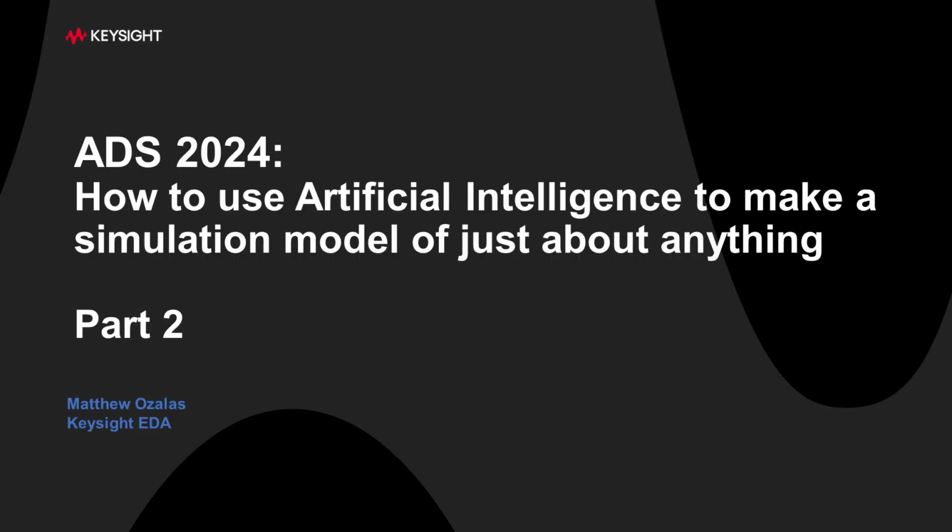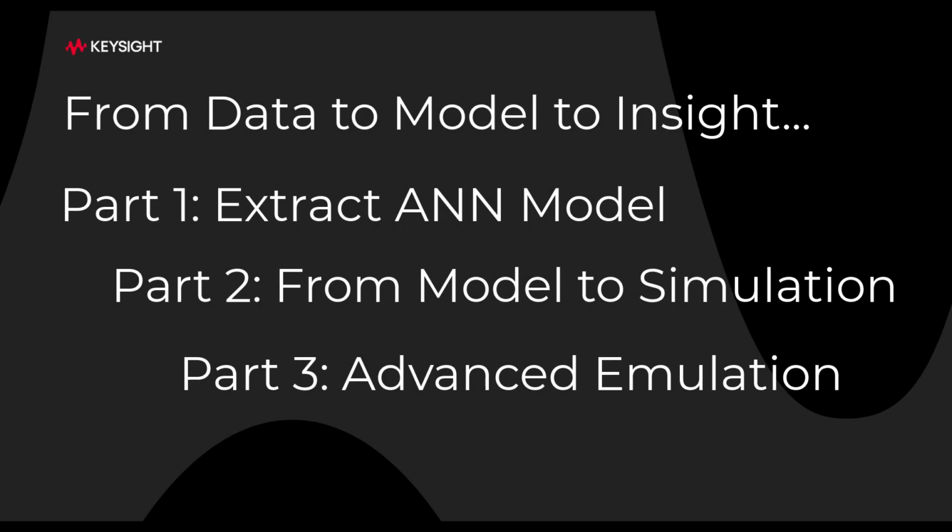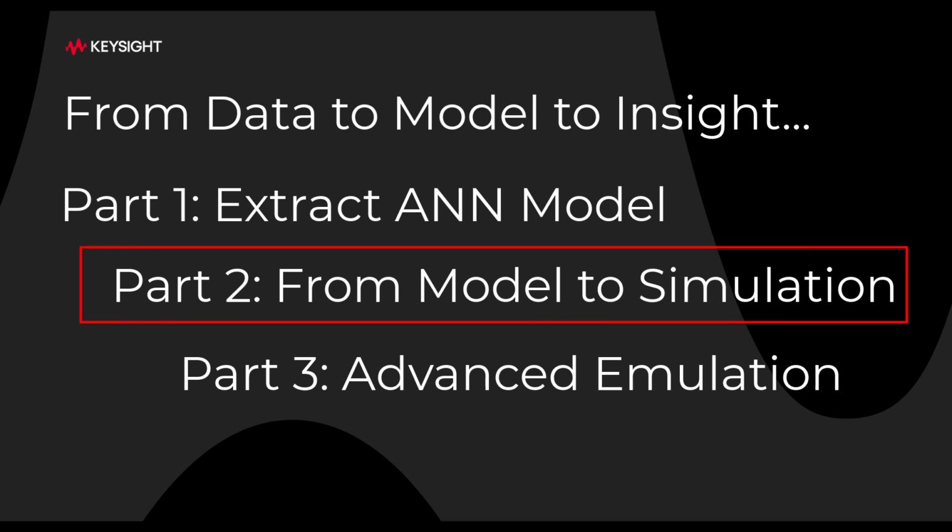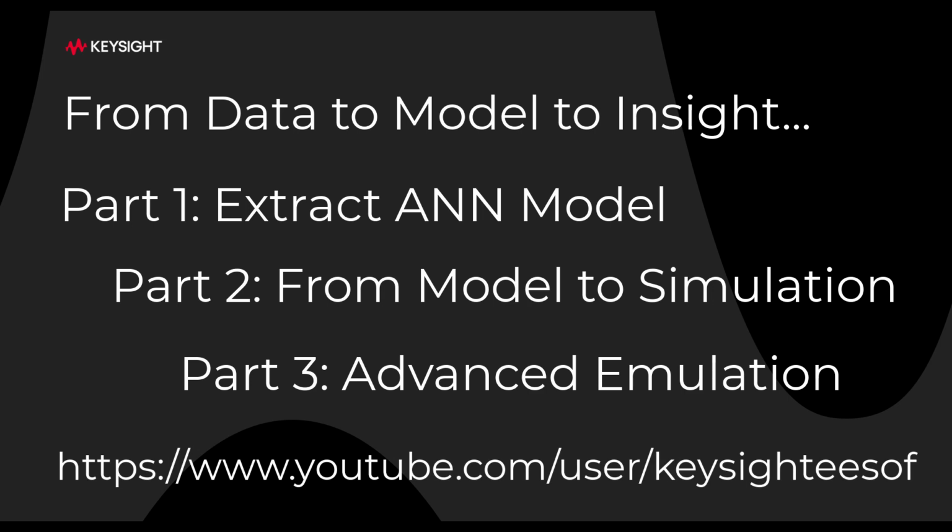This is part 2 of how to use artificial intelligence to make a simulation model of just about anything. In part 1, I showed you how to make a Python script which trained an artificial neural network model on some random data. In part 2, we're going to find some more realistic data and extract a model from that, and then we'll bring this model into the ADS simulation environment. If you missed part 1, you can find it on our YouTube channel, Keysight ESOP.